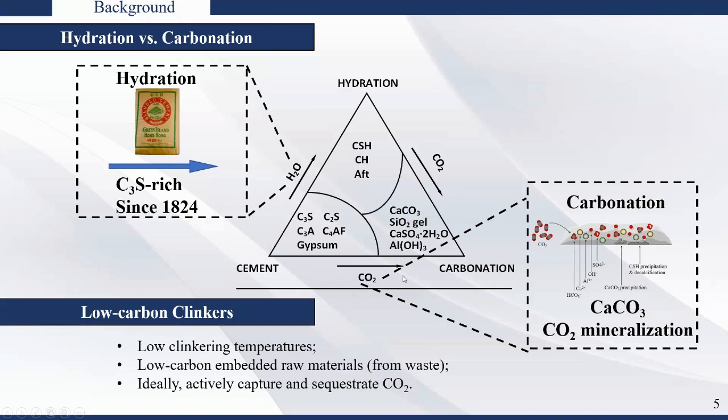That's why we created a carbonatable cement, because the cement not only has hydraulic behavior, it actually has carbonation reactivity, which means that the cement can not only react with water, it can also react with CO2 as well. We call it carbonation. During this process, CO2 is transformed into calcium carbonate. We call this process CO2 mineralization, because calcium carbonate is also called limestone. Like I said, it only decomposes at high temperature, greater than 800 degrees C. So it's very stable, and under normal conditions, we call it permanent CO2 capture and sequestration.